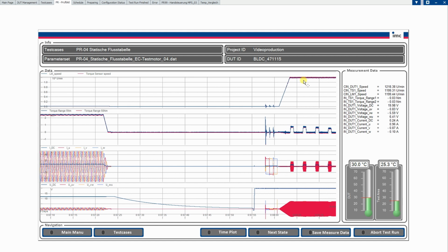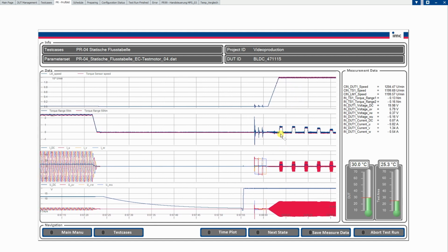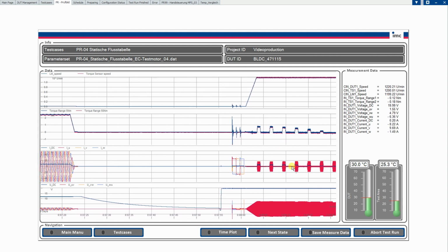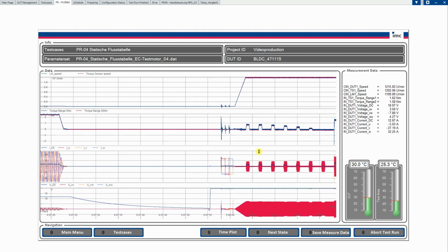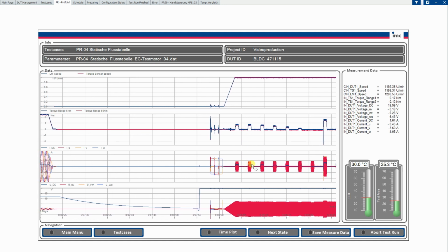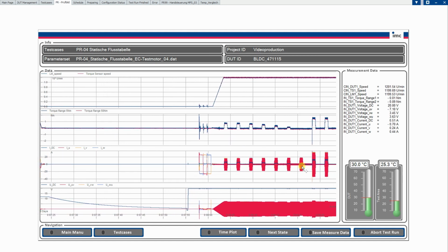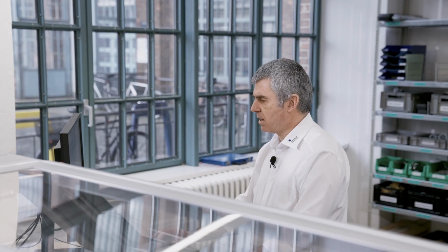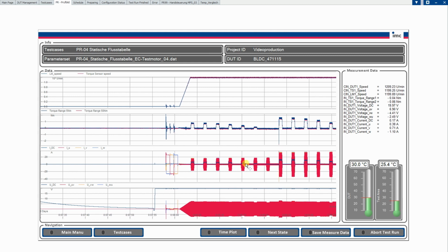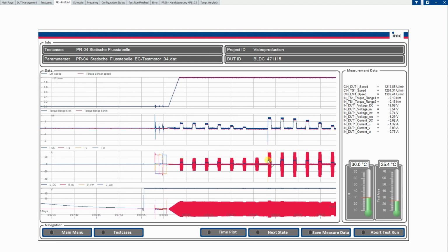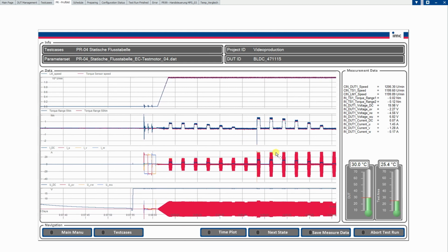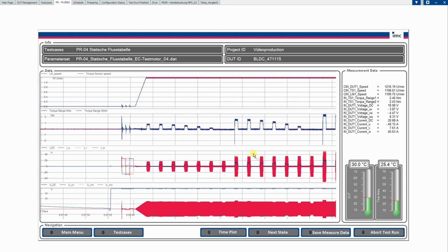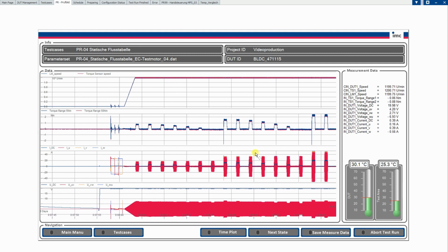In this configuration, it is about 1200 RPM. We see that the torque is varying on certain current levels here, which means we have a set of 1, 2, 3, 4, 5, 6, 7 torque points, current points, where ID, IQ are varying. And after this, we raise the current, make again the 7 points with a variation of the current in ID, IQ direction. And this is going on through all defined current values.